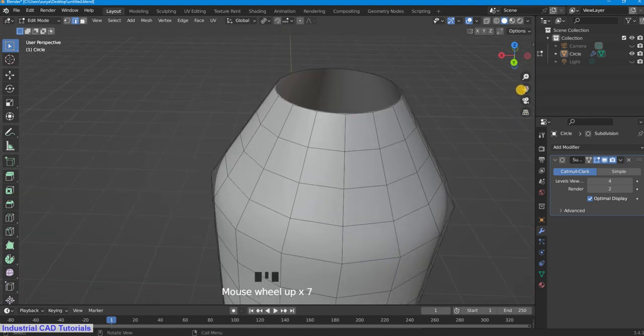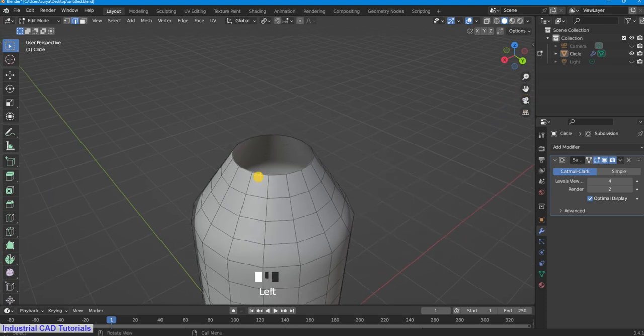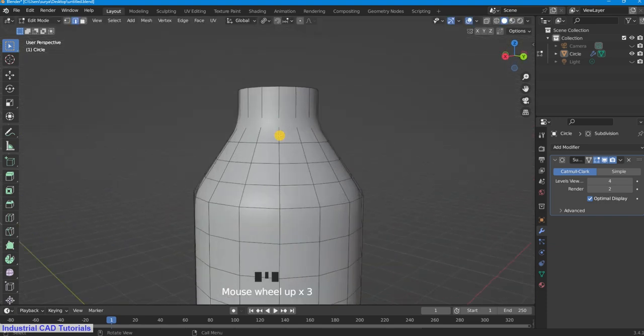I want to create a neck on the top of the object by pressing edge select with the Shift and Alt keys. I am selecting the edge and extruding this somewhat along the Z axis onto the top. It's fine. I want to create some loop cuts here.